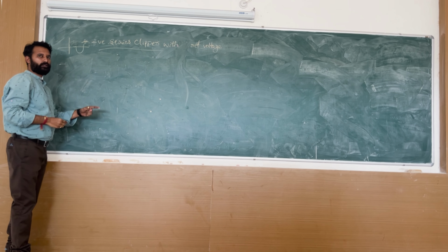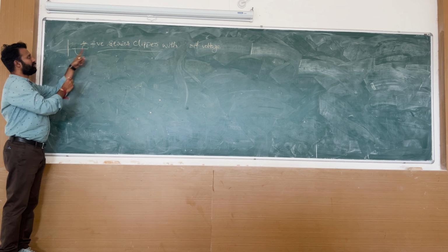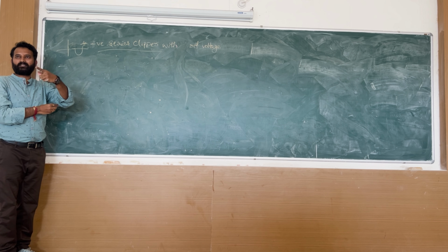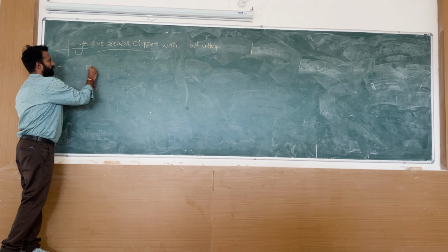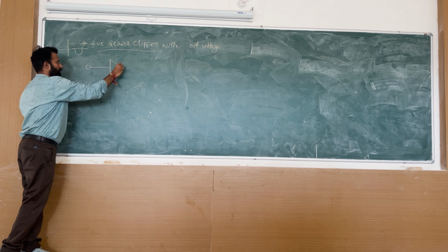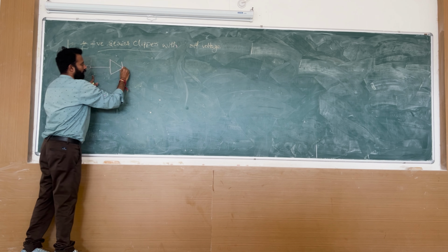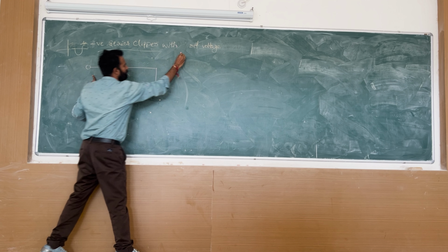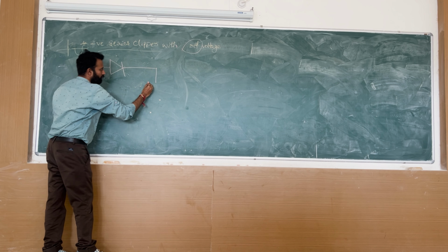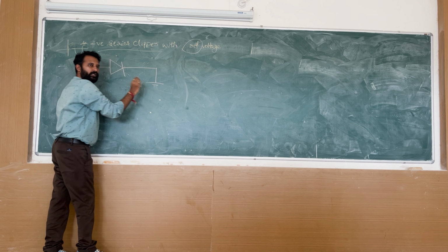Okay. Listen here. If it is a negative series clipper, how will your diode start? Positive end. Your diode will start with the anode end. And I am telling you my topic is with reference voltage. You need to draw a reference voltage here.